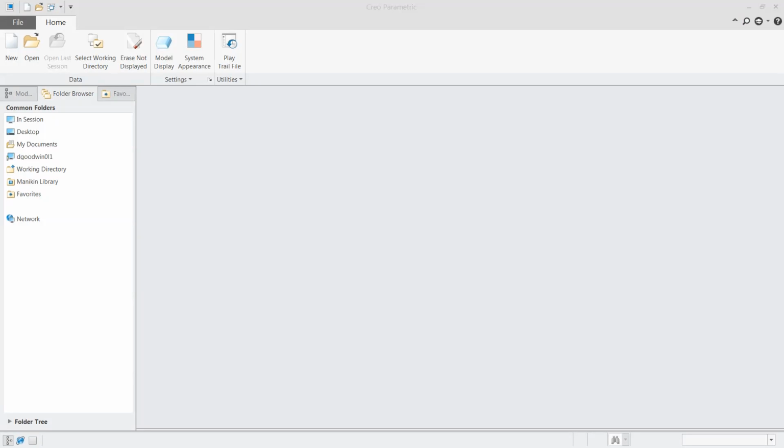And next question, can we use these features on SolidWorks? So I'm wondering if they're asking if this GD&T extension works with SolidWorks. If you were to pull a SolidWorks model into Creo, you'd be able to lay out annotations on it. Whether or not those annotated features would pass over into the SolidWorks environment would depend on SolidWorks' ability to work with Step AP 242.